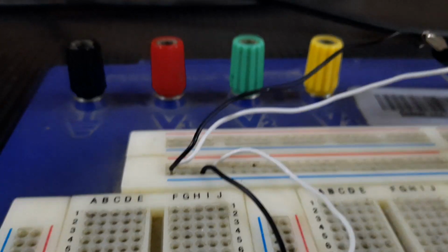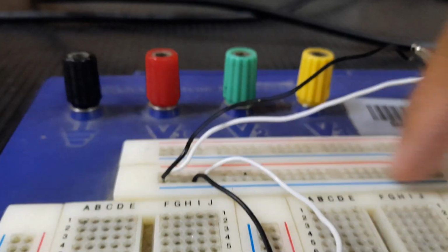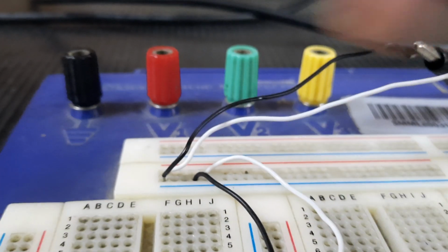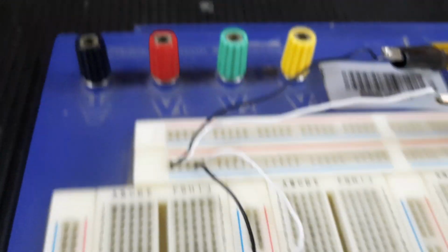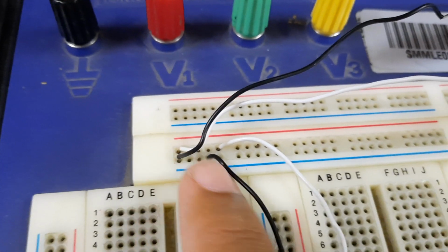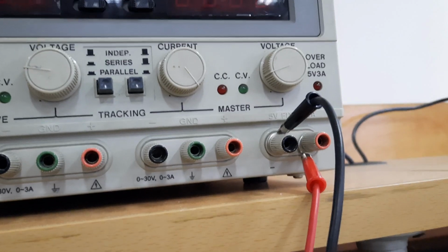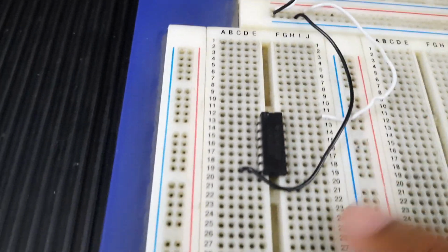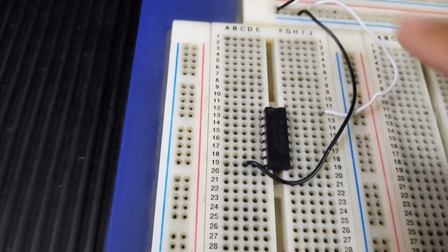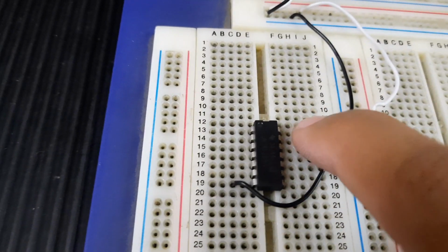Okay, so first step, I have given this whole row 5 volts so that I can pick 5 and 0 whenever I want in the circuit. See, I have given this whole row 5 volts with the help of this power supply, using the fixed power supply because I need 5 volts. And then for powering up the IC, I have simply taken the voltage from here. So 0 volts connected at pin number 7 and 5 volts connected at pin number 14.